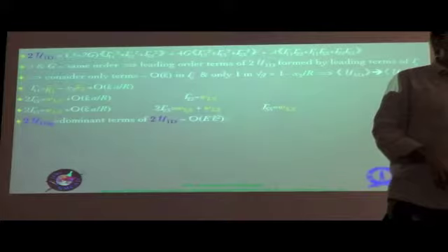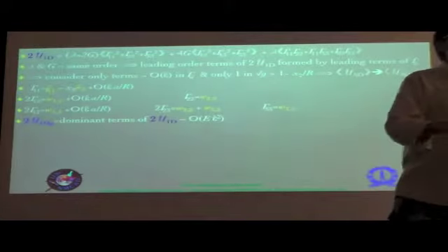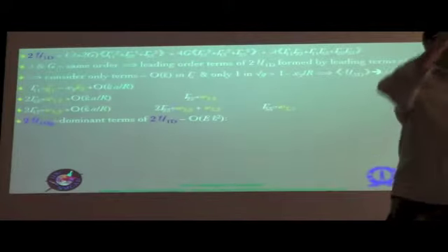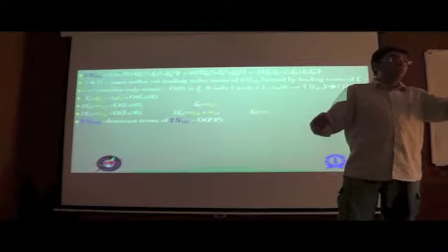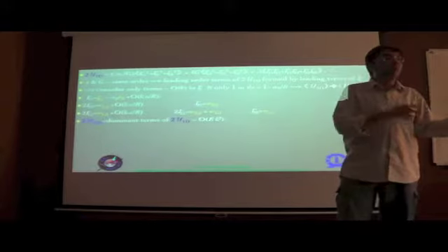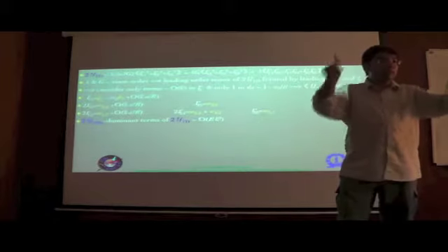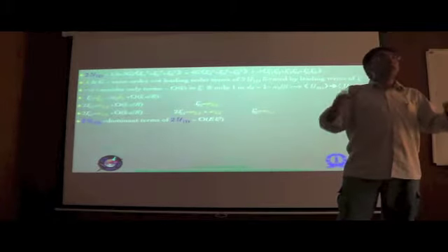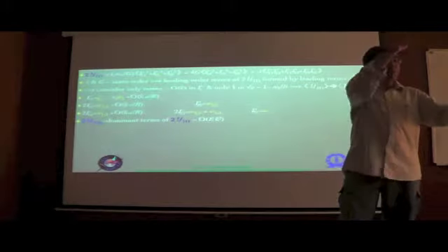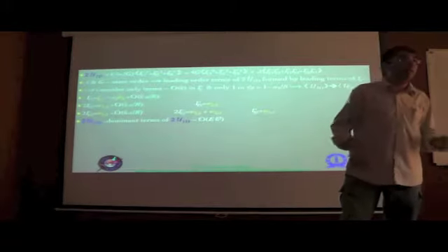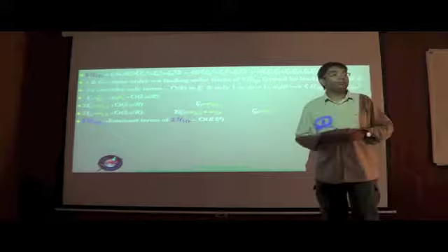Exactly. Right. So that is essential if the matrix D had terms which were of different orders of magnitude. So in such a situation you would have to do that. But here, because lambda and G are of the same order of magnitude, therefore all the non-zero terms within the D matrix are of the same order of magnitude. So instead of expanding out and doing it, we are doing it at the strain level itself, which is equivalent.